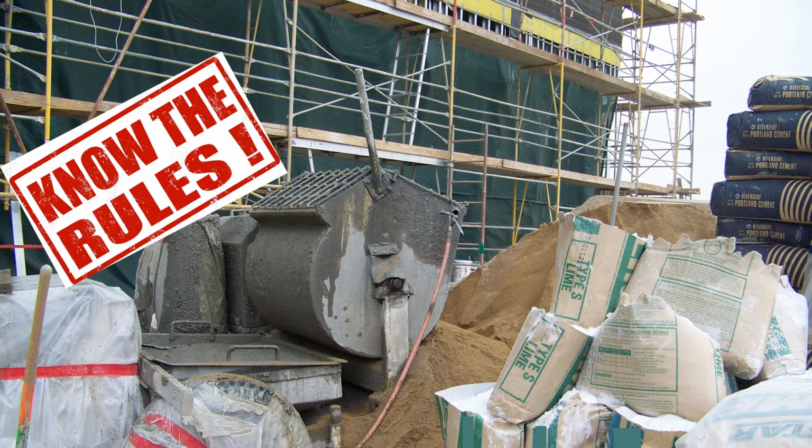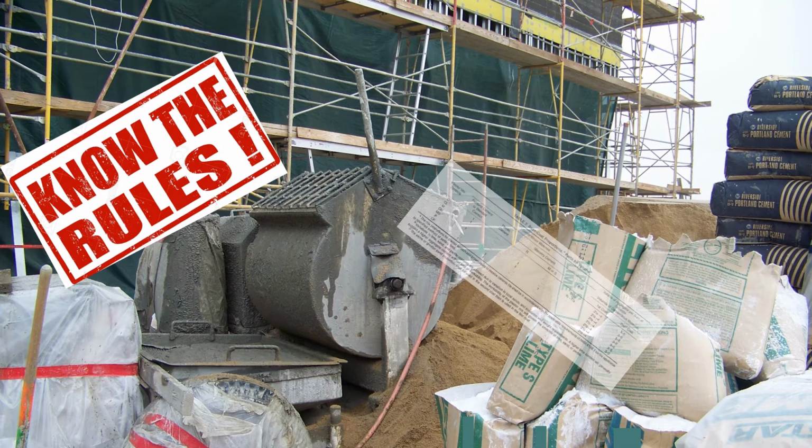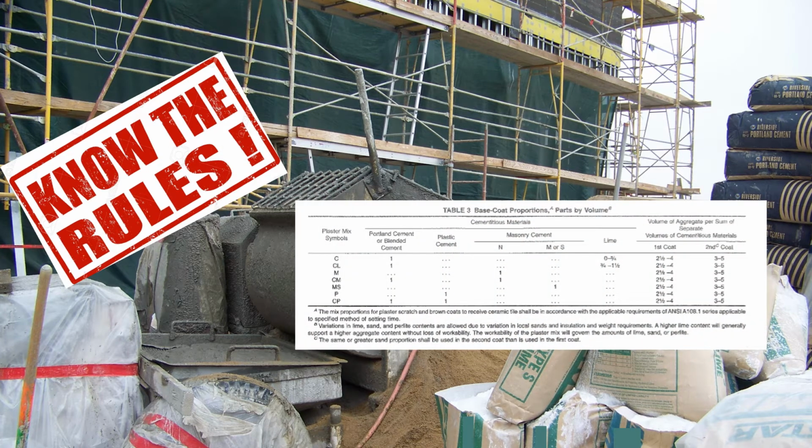It is important to know there are rules to selecting materials and ratios for mixing. Generic 3-coat stucco offers the flexibility for you to mix and make your own mix on site. This mandates you follow Table 3 in ASTM with regard to materials selected and proportions used. It is important to know the rules. The proportions are listed as parts and may be added by volume.